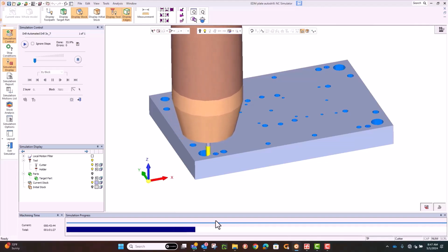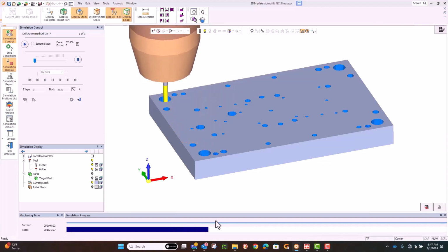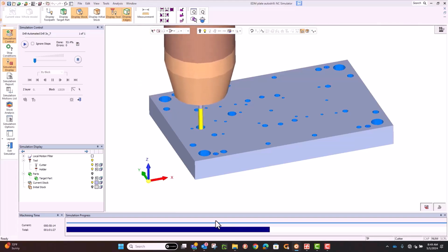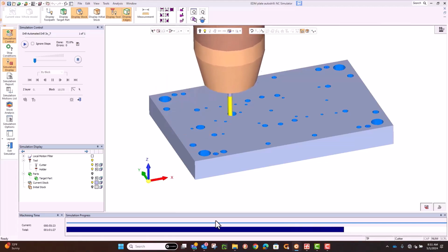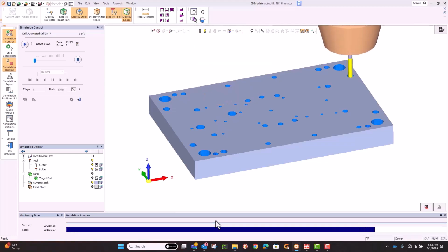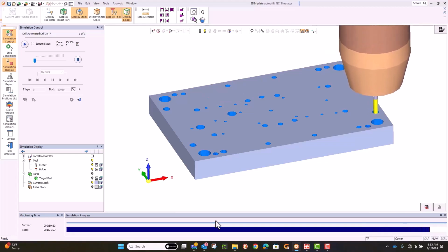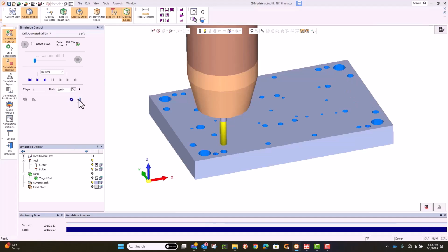It has the capability of doing every type of hole: threaded holes, counterbore, chamfered holes, backward holes, gun drill holes. All those are available, and it organizes the cutter. So if I have a drill hole, like a 201 hole, that's going to be a clearance hole for a quarter 20 tap, or I'm sorry, a drill hole for a quarter 20 tap, but it can use that 201 somewhere else. It'll do all the 201 holes, then come back and do the next drill. So it's a smart way of doing the automatic drilling.